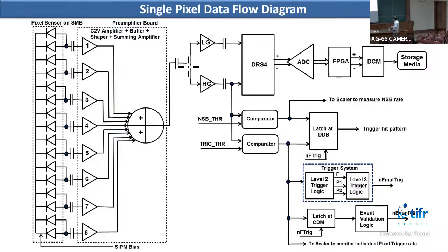Okay, to avoid that as much as possible. So this first stage coupling is not there, I forgot to remove this one. Coupling is at this stage. This AC coupling is removed. The basic thing is, if some offset is coming, that will reduce our dynamic range. So for that purpose we use it. Here this low gain and high gain amplification is done in 2 stages, and between these 2 stages we employ this AC coupling.